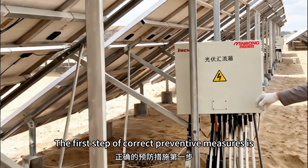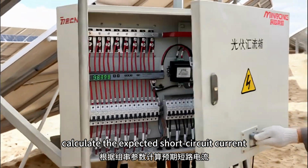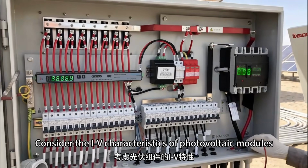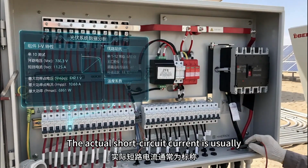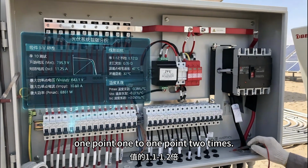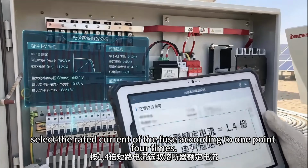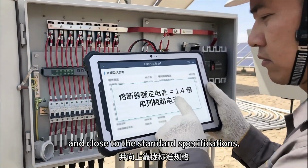The first step of correct preventive measures is to calculate the expected short circuit current. Consider the IV characteristics of photovoltaic modules, cable impedance, and temperature coefficient. The actual short circuit current is usually 1.1 to 1.2 times. Second, select the rated current of the fuse according to 1.4 times and close to the standard specifications.